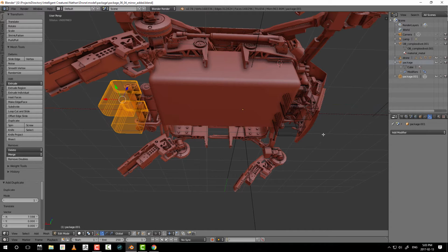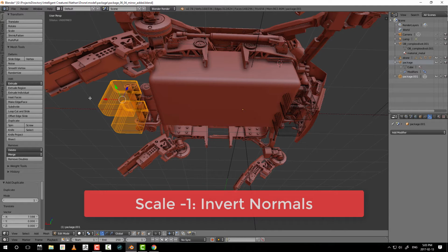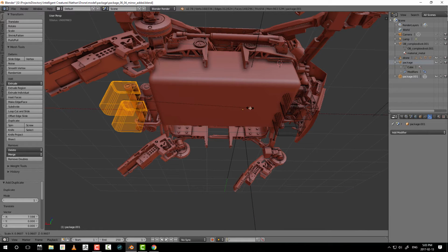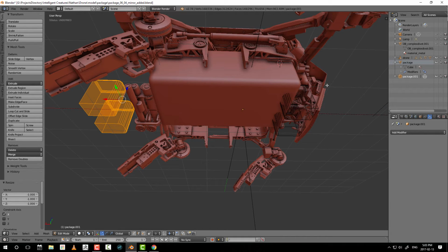X, and now I'm going to want to scale on the -X axis, so you can see the X is pointing here. So I will press S, move the mouse to interactively scale, but I want to constrain the scale only to X. So I press X to do that, and now if you look at the bottom left of my screen, you'll notice that the scale values are changing. I'm going to press Control to constrain it to 0.1, and when I get to -1, I want to left click, and now I know that I have in fact mirrored the object.